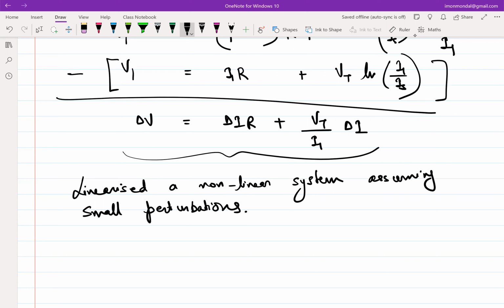We had some system set up which had a current and voltage relationship of V1 and I1. I perturbed the system and applied this incremental delta V on top of it. And we argued our way through and figured out that the relationship between the incremental voltage that I applied and the incremental current that resulted is linear. So now when you are in the linear domain, you are in safe territory, right?